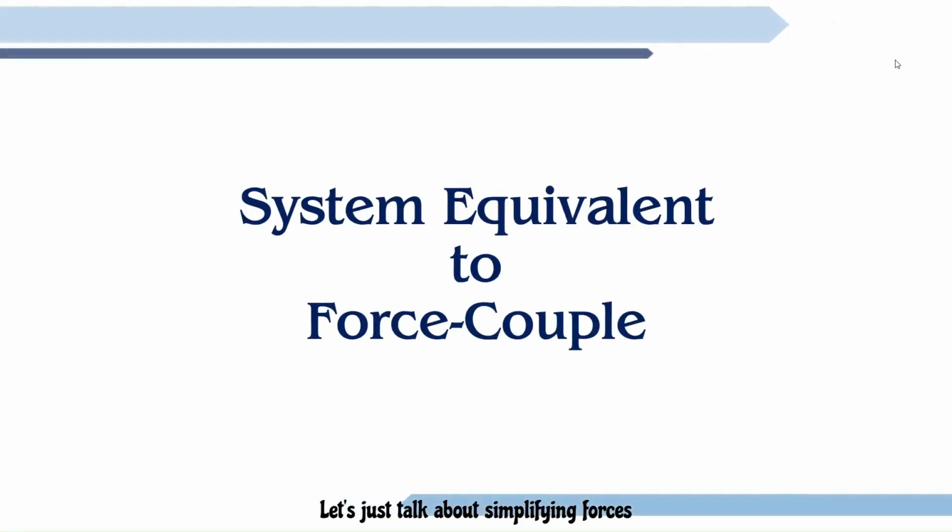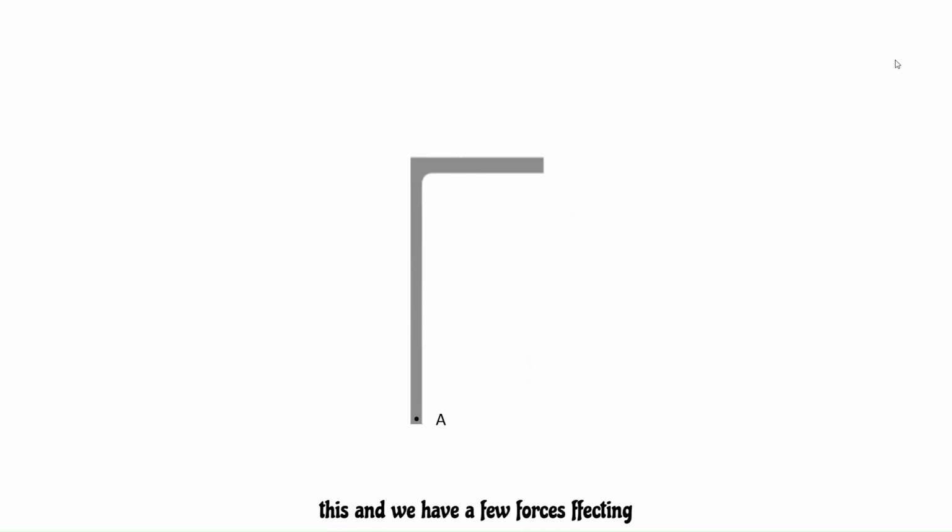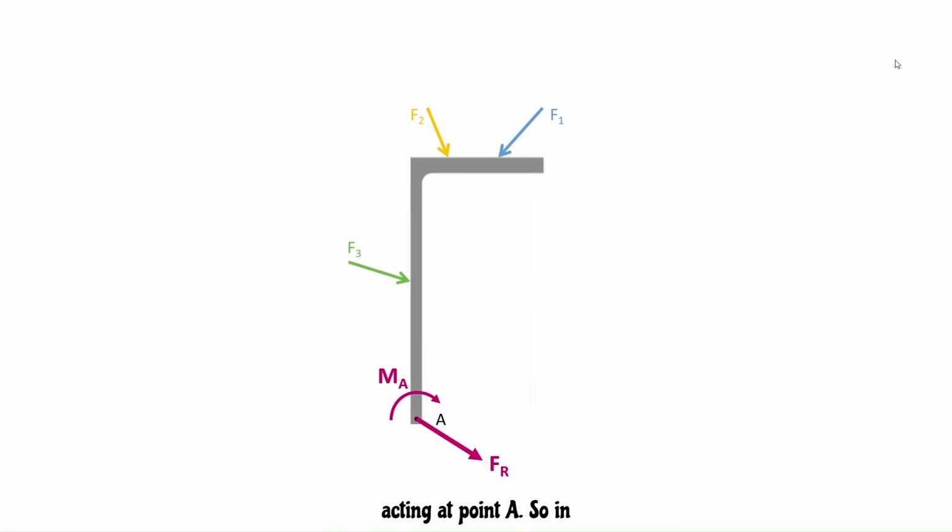Let's talk about simplifying forces and moments. Imagine a metal post like this, and we have a few forces affecting it. Let's say we want to find an equivalent force and a couple moment acting at point A. So, in simple terms, we want a single force and a single moment that represents all the forces and moments